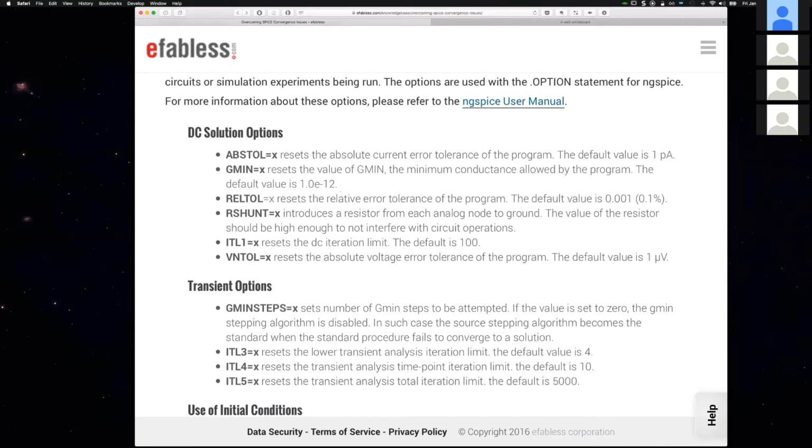So you always have to understand the value ratio between such a Gmin factor and the impedances of the nodes you're looking at. Making it too high, you're basically putting a filter on what the simulator can and cannot do. My recommendation in all these cases is to run multiple values and understand the sensitivity of the circuit to the specific parameter.